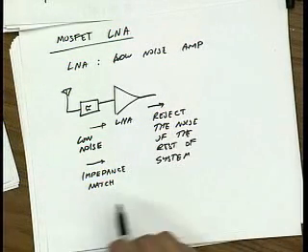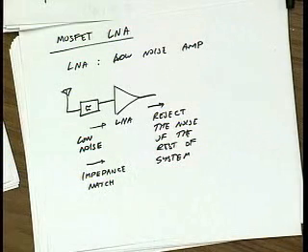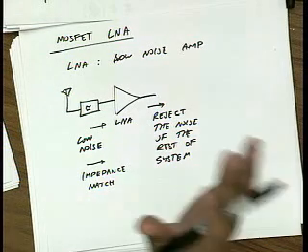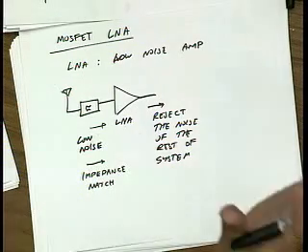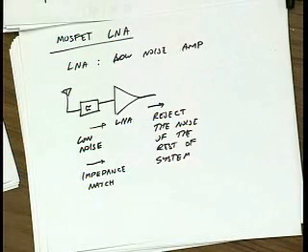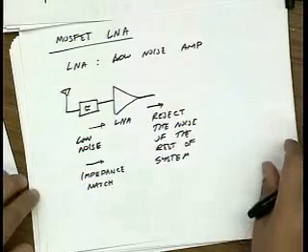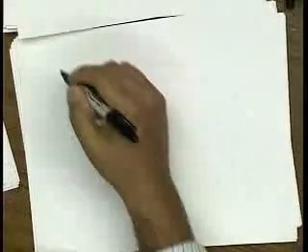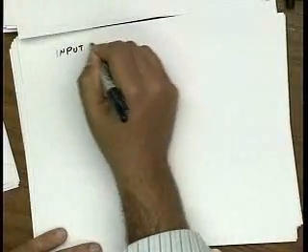Now the reason I bring this up is because it's a very controversial topic. Almost anybody who takes an RF course at some point says, why do I go through all this trouble to match the input impedance of an LNA? Let's say I'm willing to give up a little bit of power gain and not put a matching network down. Makes my life so much easier. Why not do that? Well, that's one of the reasons why you need to match the input impedance of an LNA. Okay?